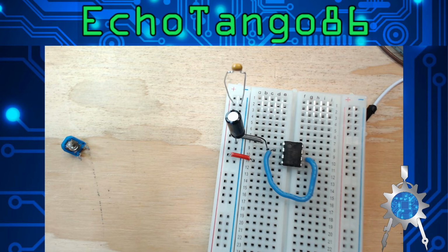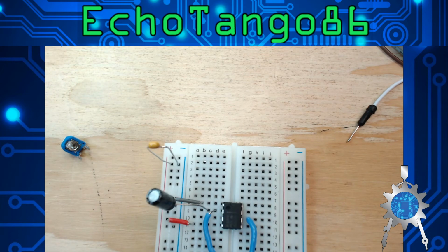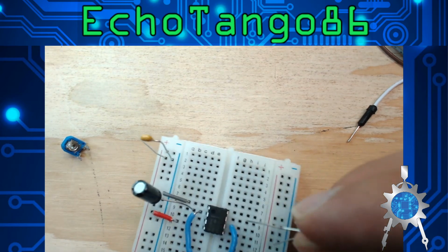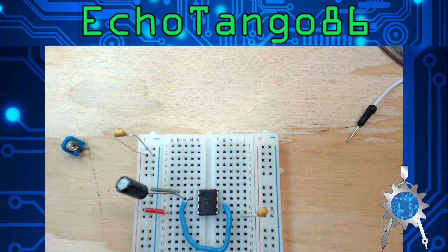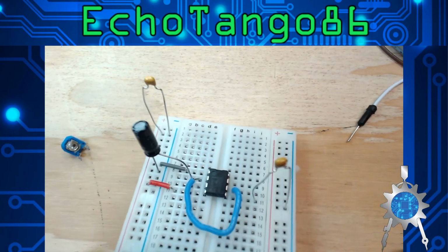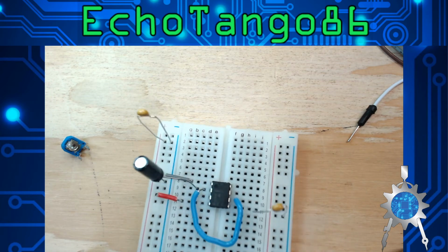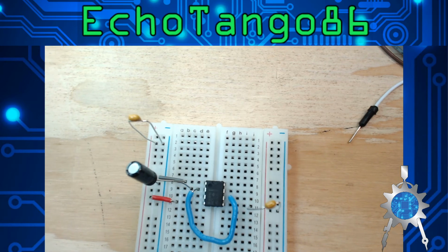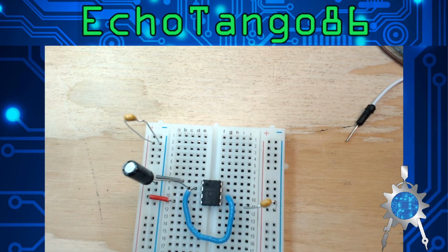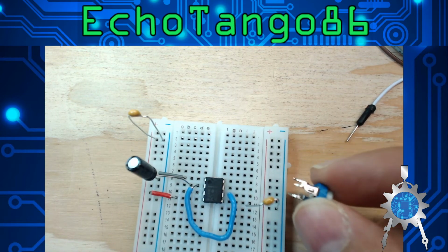Pin 5 is our other capacitor that goes to ground. So we're going to go ahead and grab our other capacitor here, put it in negative, and connect it to pin 5. That easy. See? 5 in ground. Pin 6 is our variable resistor. What we're going to do for this here is our variable resistor.